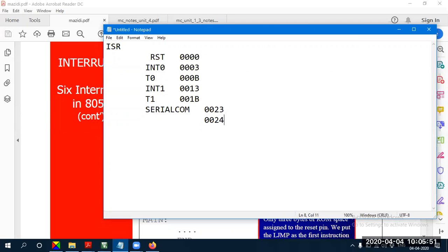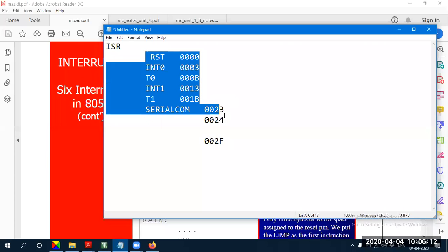Likewise, this will continue, let us say, up to a maximum of, assumption, it may even continue behind this, but the assumption is that it continues up to 0030H, excluding 0030, that is, we can say 002FH, for example. Okay, so thereby, since the ISR occupies this address, and this address is default, which we cannot change.